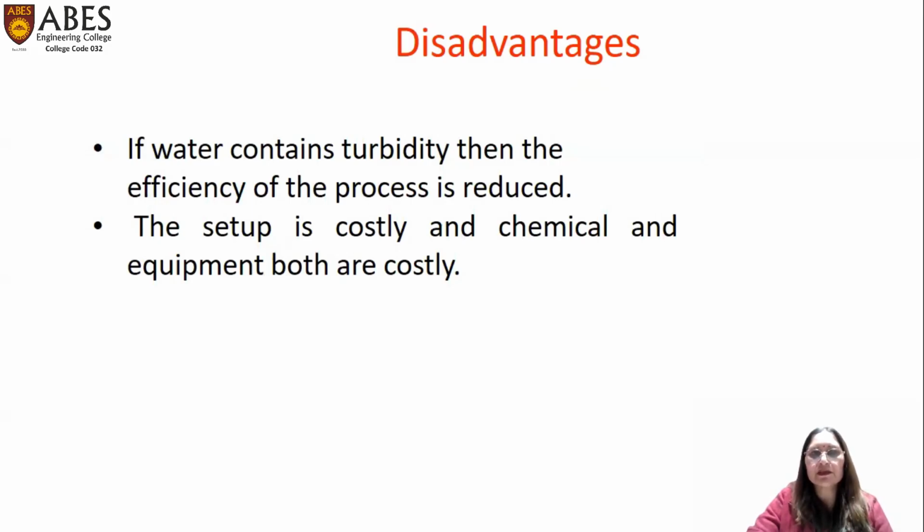Disadvantages of this process: if water is turbid, the resin's pores will be blocked and the efficiency of the process is reduced. And this equipment and chemicals are very, very costly. If we use hot water, then the resins will dissolve in it.